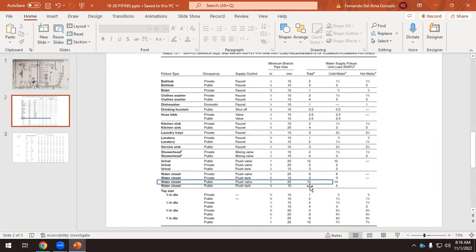Again, if you have 20 years of experience working with this, you will understand that 10 is better than 5. Because if you select 5 for your first one and there are issues, the pipe has to be thicker because there's a jam, and every other year we have to remove it. So next time I will select something bigger because you can save a lot of problems. But so far, if we have these 2 options in the table, either option is good. So we have selected this, and for the lavatories, we have selected this option. So what's next?